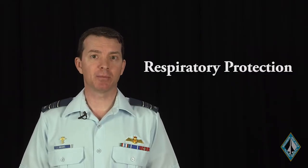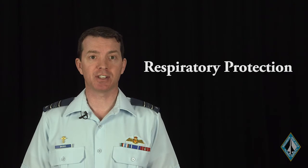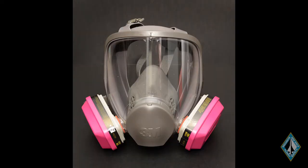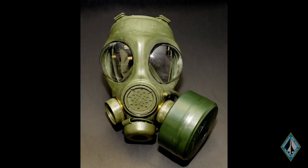Filtration masks are the most common type of respiratory protection used on aircraft crash scenes. Filtration masks primarily prevent the inhalation of harmful physical particles, such as burned carbon fiber. However, some filtration masks can also be equipped with filters to prevent exposure to specific chemical hazards. Filtration mask options include N95 type dust masks for protection from inhaled physical particles only, half masks with appropriate filter type, full face masks with appropriate filter type, or, for military members, issued C4, C7A gas masks with appropriate canister.